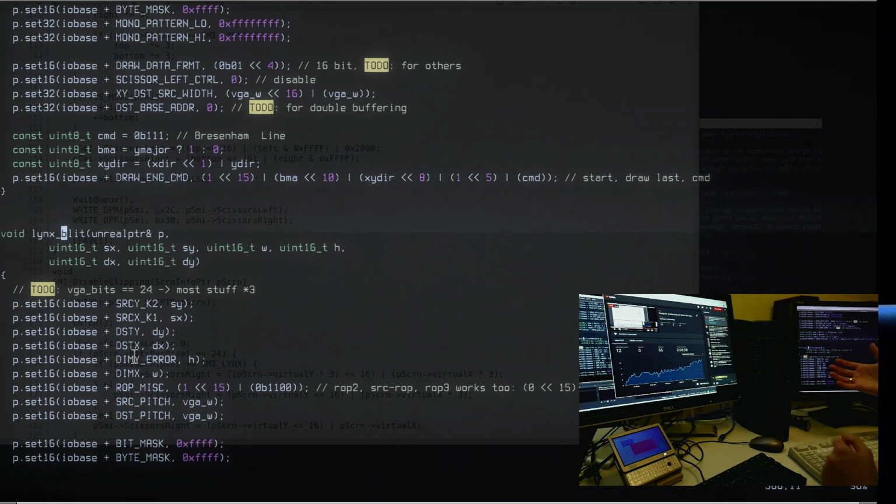Even other sound drivers have this kind of stuff sometimes, maybe even for the RME Digi cards that we also already did programming here live on YouTube, because sometimes even on the card you can't read the registers back. So some command registers on the RME Digi32 card you can only write but never read, and similar stuff. So I'm actually surprised that in a real sophisticated, modern software architecture, you would make this one register shadow class thing and reuse it everywhere. Somehow that's not happening in either the Linux kernel or Xorg. Anyway, this is why, yeah,